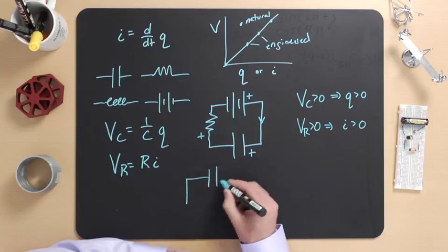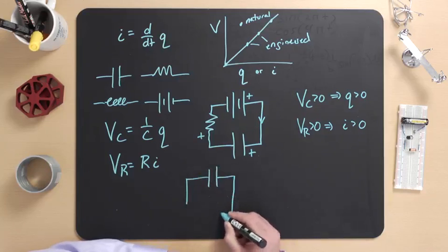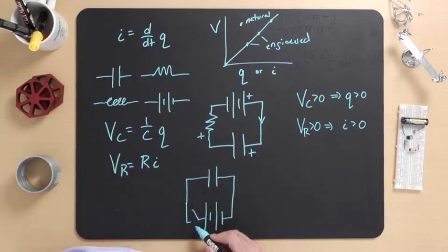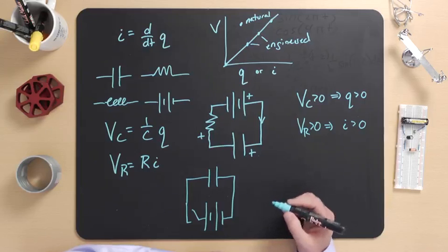Lastly, sometimes our expectations about electrical systems will not always be well aligned with our understanding of the idealized elements. As an example, consider this very simple system. I have a capacitor, I have a battery, and I have a switch. So this switch can be open or closed. When the switch is open, the circuit is not complete and there is no charge in the capacitor. However, the moment that the switch closes, this idealized system predicts that the capacitor will be instantly charged because its voltage V sub C will be instantly equal to the battery voltage V sub B.